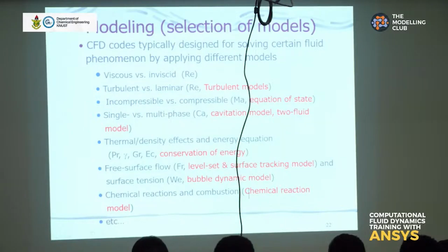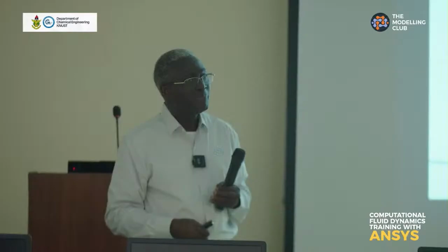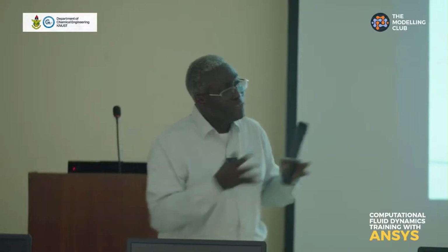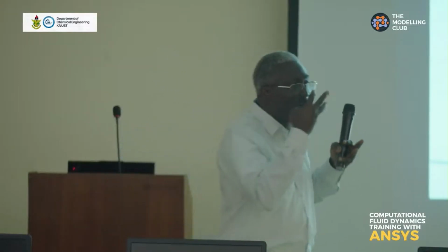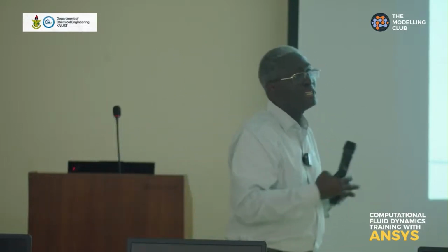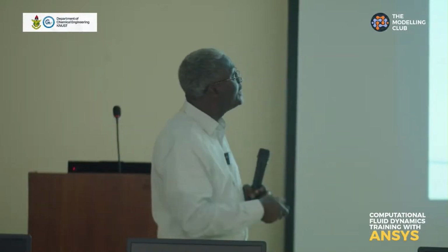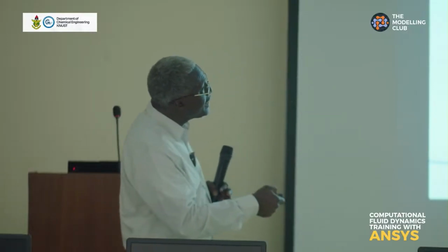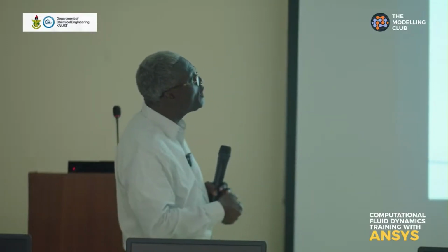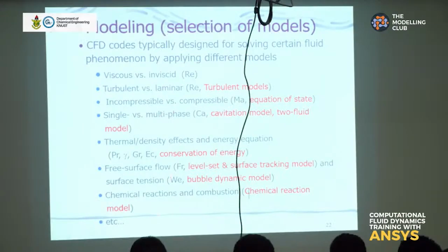Now, if you are, of course, deriving that from scratch and solving it on your own, then in your derivation you are taking that into consideration. But if not, then to accurately produce correct simulation results, you have to have a clear understanding of the phenomenon that is taking place so that you turn on or off any of these modeling features within your CFD program.